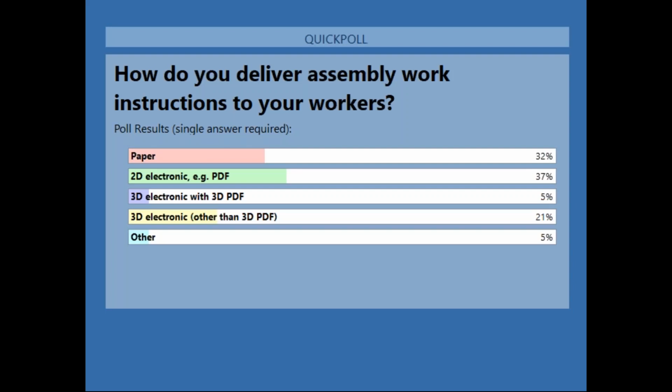Okay, that's a good point. We haven't talked about that. One of the things that makes XVL so powerful is that it compresses very large CAD data 100 times or more. So a gigabyte CAD file will be down in the megabytes in XVL. And typically that makes it small enough to be able to use on even lightweight laptops. And so you can use your original CAD data, your original design data with all of the parts right there on your screen. So when you're building the mBOM, when you're building the process tree, you have all of the geometry at your disposal. Other systems that can't handle that large data have to break the model up into smaller pieces, or only have assembly instructions for certain parts of it at a time. So by compressing the data down 100 times or more, XVL gives you the ability to work with much larger models when making your work instructions.